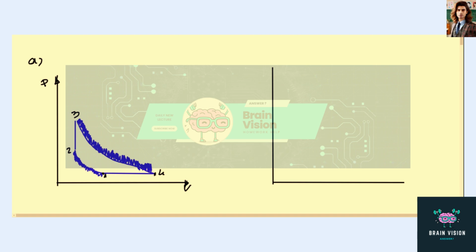And we must remember that for a PV diagram, an isentropic transformation has no exchange of heat with the surroundings. Therefore, we have heat entering here and leaving here. Well, this is the PV diagram.